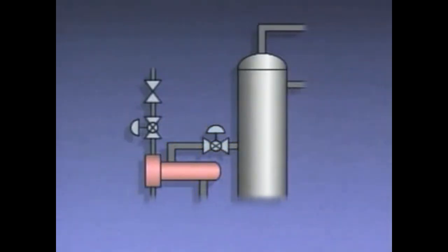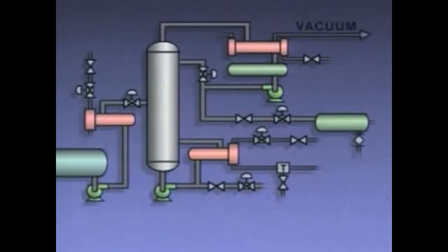To ensure that the feed flowing to the column is heated properly, a control valve in the preheater steam line is gradually opened to bring the preheater up to operating temperature. At this point, heat can be applied to the mixture in the reboiler. To do this, a temperature controller is used to open a steam valve to the reboiler. As the reboiler warms up, it transfers heat to the circulating mixture.